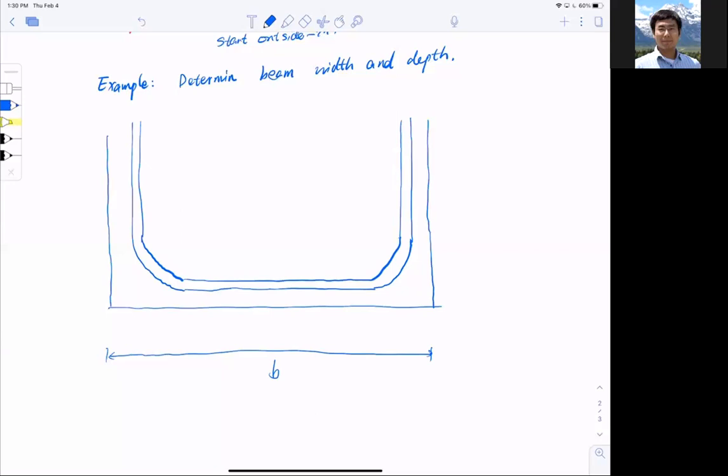But before I put my bars down, here are some details. Remember I said this is going to be a semicircle here, because that's how I bend my stirrups. If you were here in person, I would start asking questions. How many of you have seen a bender before? I actually bend the bars, so I've seen the bender before. When you bend the bar, it comes in all straight. You need to force it to circle around a steel pancake, a steel disc. The disc has a diameter, and that is what we call the bending radius of the stirrups.